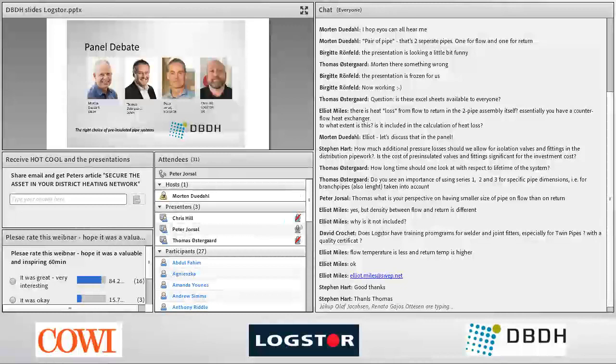Okay, go ahead. I would like to say that you have to base your decision on calculations. So you owe yourself to do the calculations and then make your choice based on the calculation and based on the assumptions that you have made. So I really don't want to say that in these examples it's always series 1 or series 2 or series 3, because then I very much tend to do what always has been done. So my advice is really to say, do the calculations. I could say that for very big pipelines, it's normally more difficult to calculate an interesting return of investment with very high insulation thickness. But my advice is always do the calculation of different pipe scenarios and then make your choice. And really spend the time finding the right assumptions.